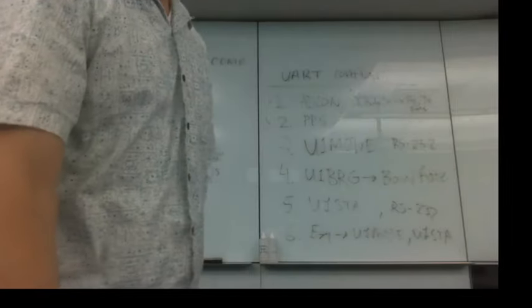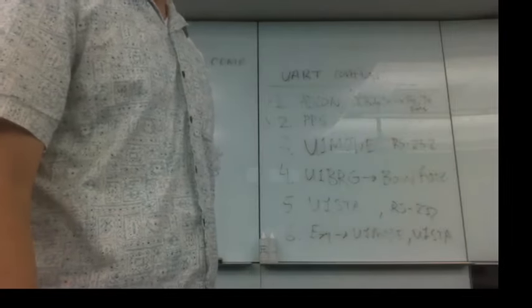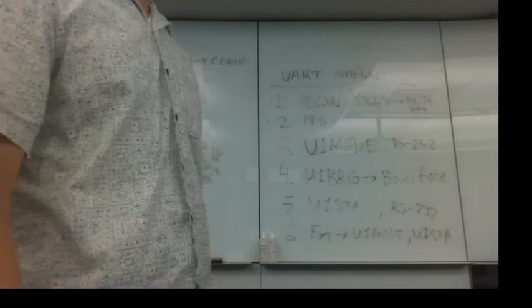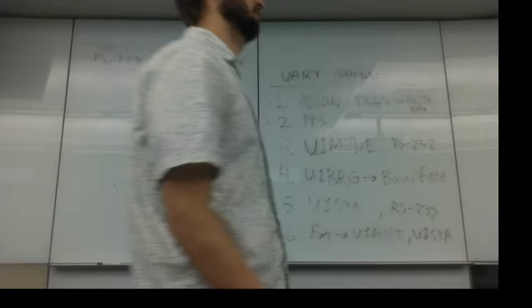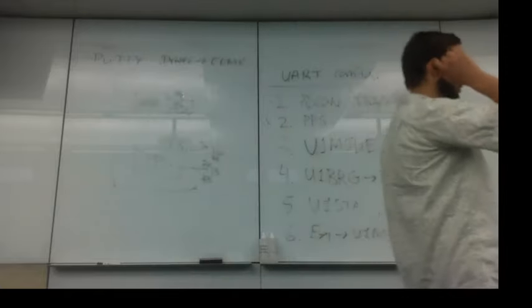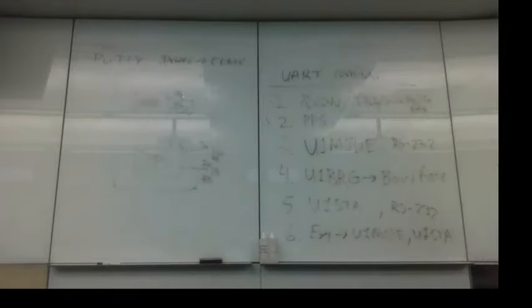So if we use BRGH equals 0, what's the error for 115? Yeah, negative 3% error. And if you look at the actual baud rate, we're off by 4K. So I'm going to guess that that may be allowable by most modern computers.